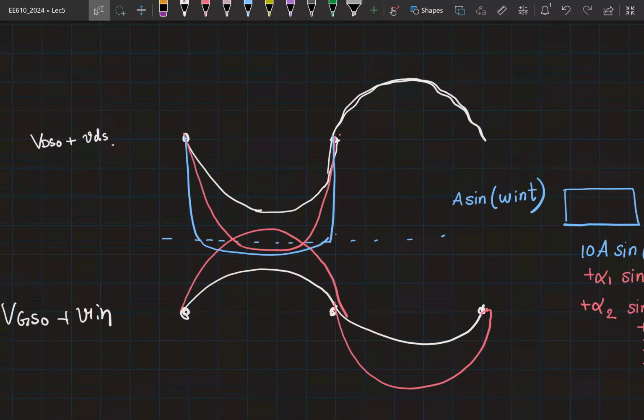if you give a sine wave which is larger than this A max 2, what happens at the output? You will have a regular amplification around it, but from that point onwards, there is no current, Gm has dropped to 0. Therefore, even when your input is reducing further, you don't see a corresponding reduction at the output.